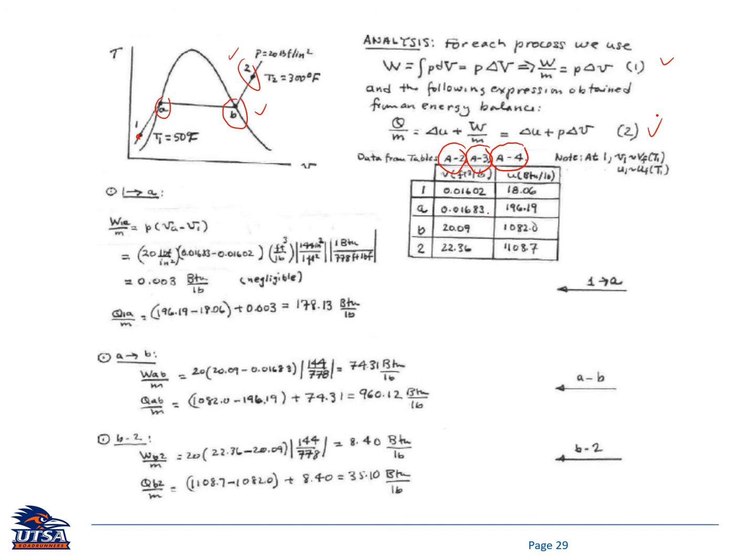Okay, in here at state number 1 we use this approach so that V1 equal to Vf at the same temperature, and also U1 equal to Uf at the corresponding temperature, which is T1. So you can make a simple table here to get V and U at state 1, A, B, and 2. So once again, use a different table here to get these properties.